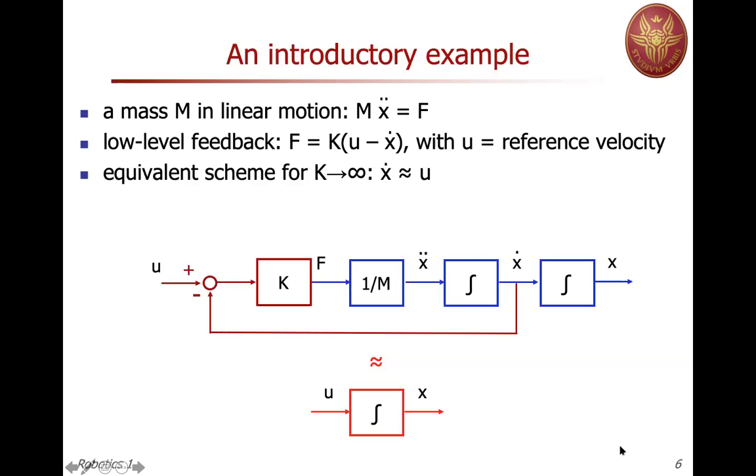Okay? And this is true if you have very large gains and if you can tolerate very large gains. Of course, in practice this is not true because you have saturation, so you cannot bring k to infinity. But in principle, if this is true, the whole loop between u and x dot can be eliminated, can be substituted by a 1, if you wish. So what remains is just the integration of x dot into x, but x dot is exactly equal to u.